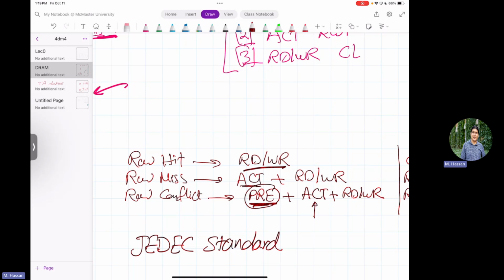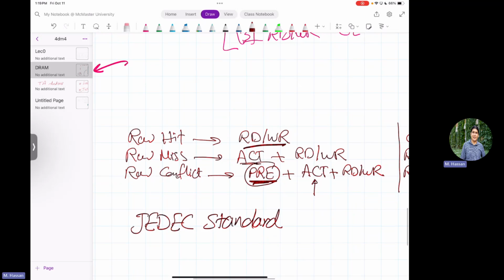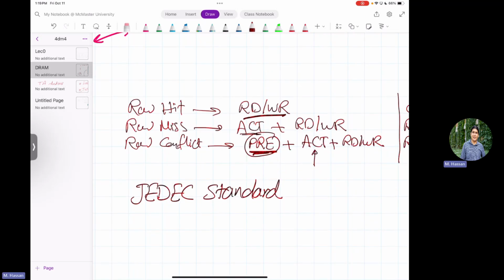This standard defines your banks, the chip itself, which is very natural, but it also defines how you should access the DRAM. So the CPU manufacturers designing the memory controller will know early on from the standard, if I want to put DDR5, whatever speed you buy, as my main memory on that DIMM slot in my desktop, this is how I should operate my memory controller.